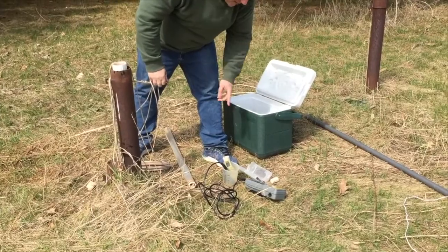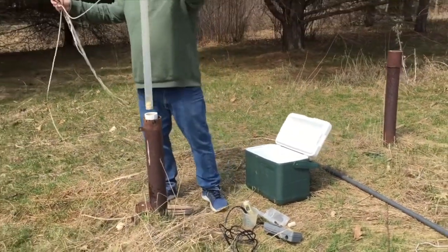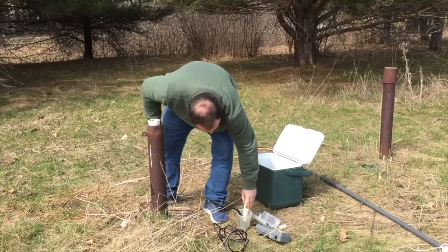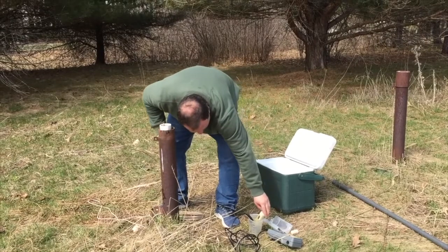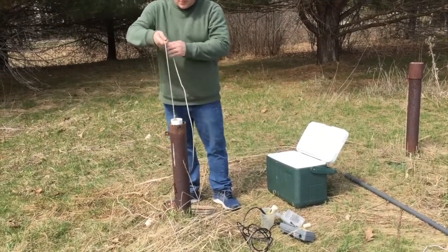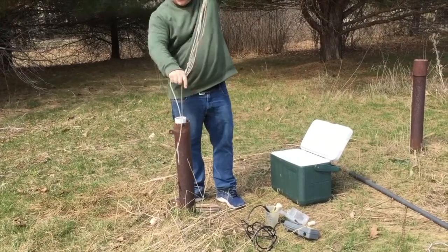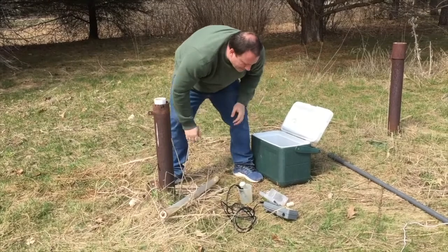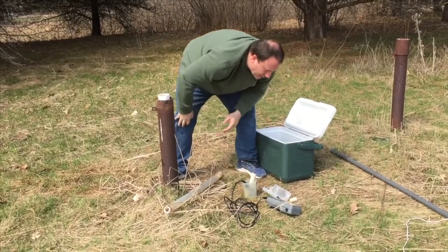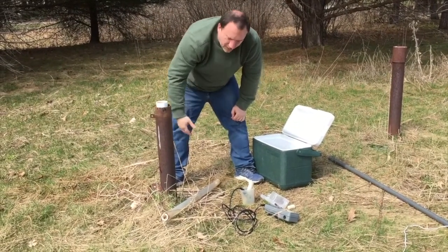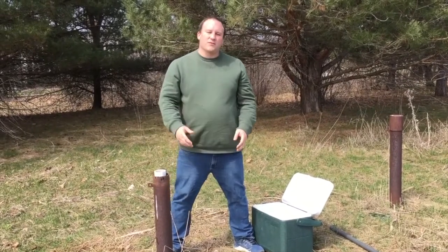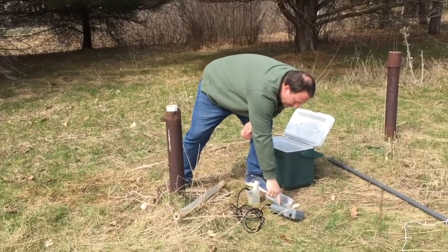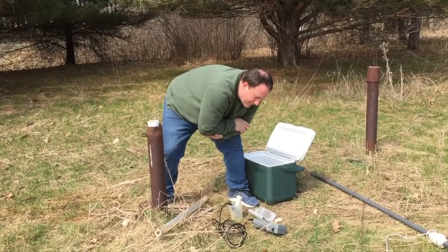.1 degrees Celsius, and it's rising real quick. I'm going to do one more bailer just to get a fresh amount. Let that thing come to some sort of equilibration. So 8.6 Celsius, I was able to get more out of it. The more you get out of it, the less this steel and the PVC is warming that water a little bit. So 8.6 Celsius, 760 microsiemens for conductivity, and 1103 microsiemens for specific conductance.